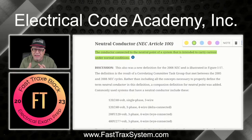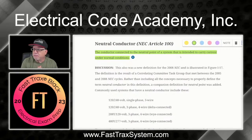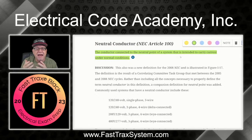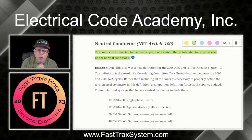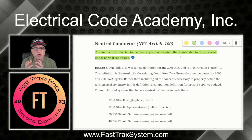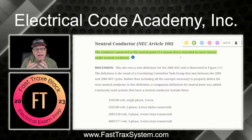In other words, when you install it and you hook everything up, you know that at any given point it could carry current. Now, typically when we work with systems in the NEC, the neutral conductor is basically sized to handle the maximum unbalanced load. And we'll talk about that in 220.61 when it comes to a calculation of the neutral conductor, especially for things like feeders and services. But it's really important to understand that the neutral conductor is designed to carry current at all times under a normal condition.